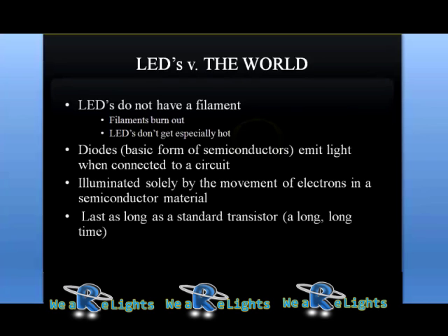Newer lamps are claiming lives as long as 100,000 hours, and over the next few years, we'll see if the practical application matches the manufacturer's claims. At this point, it's hard to prove or disprove those claims. Remember that a year, 365 days at 24 hours a day, is only 8,760 hours. To prove a 100,000 hour claim, we'd have to run the light continuously for 12 years. Since these types of LED lights are only a few years old, we only have theory to go on, and theories, as you know, don't always prove out.